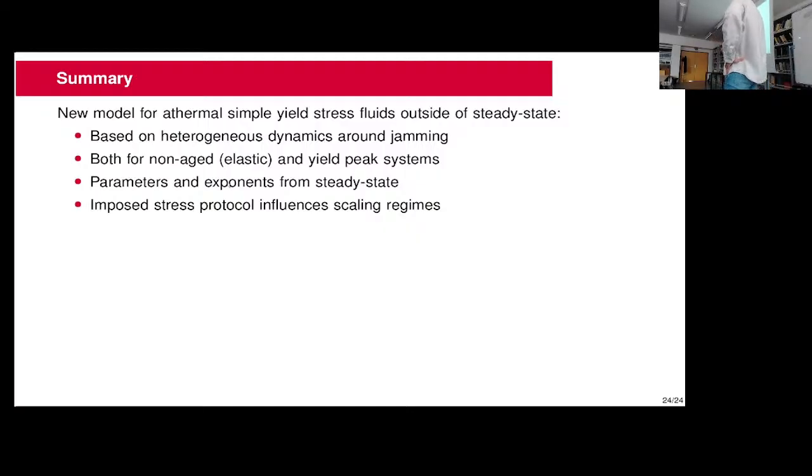We've shown that the imposed stress protocol might change the observed scaling, which is a really good insight to maybe conduct new experiments on such yield stress fluids to be able to explore either the viscosity or logarithmic and visco-elastoplastic creep regime. And I insist, all the parameters are just derived from steady state experiments.